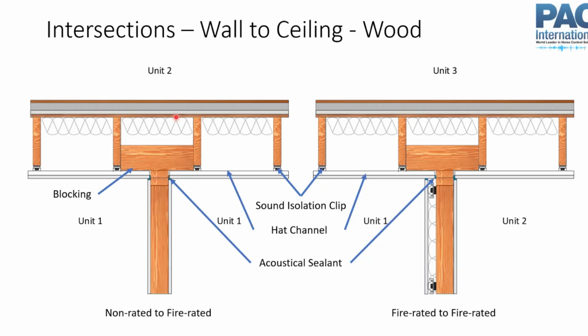Now here we have maybe some sound isolation up at the top, a mat underneath the gypsum concrete. So we do have this acoustical break here. So that's helpful. And again, this is kind of a circuitous path. So we can do that if it's fire rated, things like that. We have isolation down here too. It's a similar sort of situation.